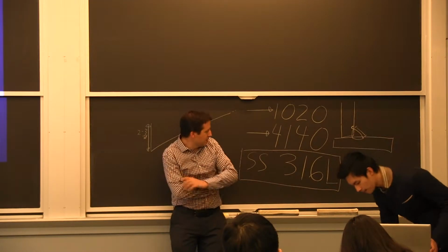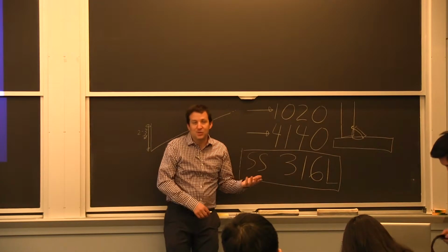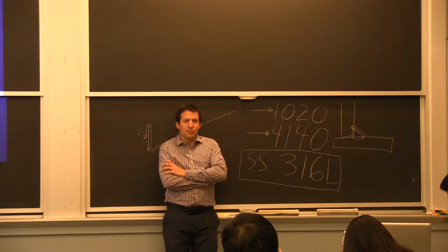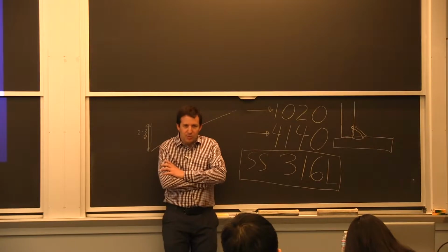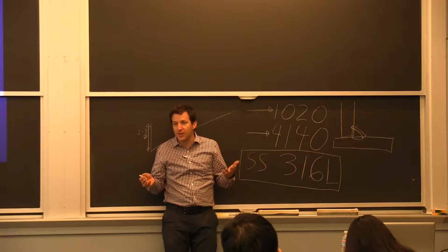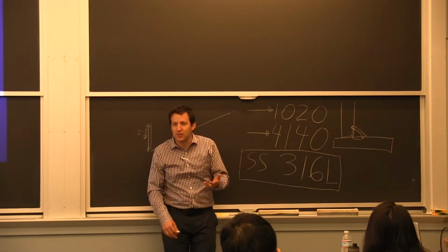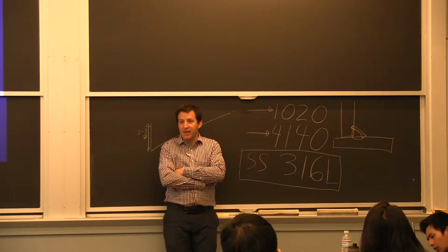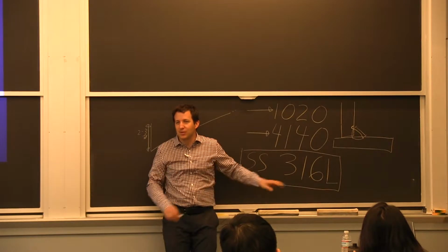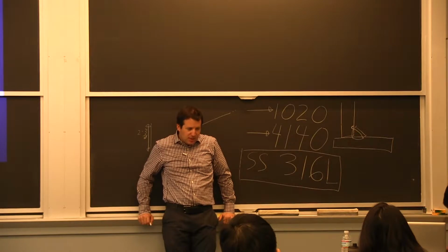Most stainless steel now, even if I was to buy a 316, will probably come as a 316L, because it's not too much more work to produce the low carbon. It avoids them having to carry both. There are no real advantages in not having the L. So even if you buy a 316, it could be a 316L. Is it guaranteed to be 316 low carbon? No. So you still want to put it on, but it's only the chemical part.